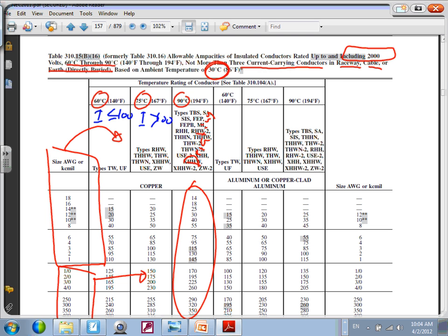These are the terminations. If you're doing commercial industrial, now I emphasize this, in the residential, if you're doing commercial industrial, Chris, you're right here 100% of the time. Can I get you guys to understand, if you're doing a commercial industrial project, 99.9% you are in this column. So the 60-degree column, almost ignore it. So that's an and statement, number one or higher.